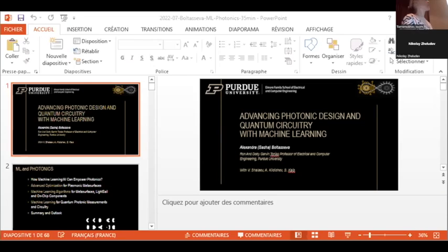We have also started with a simple design. Before we go to the design, I would like you to look at this unit cell of the metasurface that we consider. Here we have a metallic mirror, a dielectric spacer, and a plasmonic antenna on top. One very important note is, as I already said, this is a multidisciplinary problem, right? So you have to optimize many, many things. And one of the things which is really a cornerstone of many applications in photonics is your constituent materials. My group has spent decades working on plasmonic materials that are robust enough to sustain high temperatures.